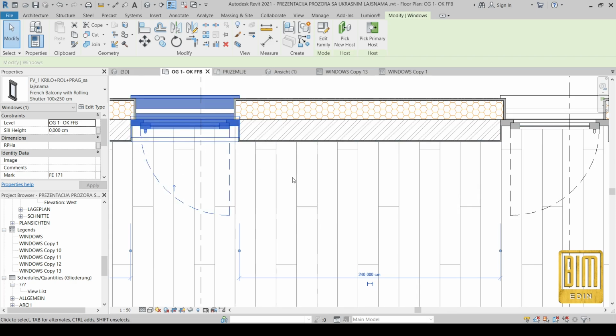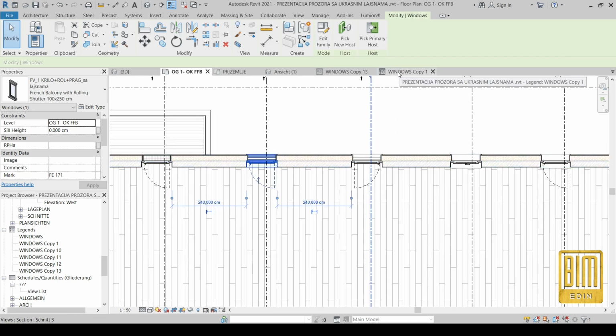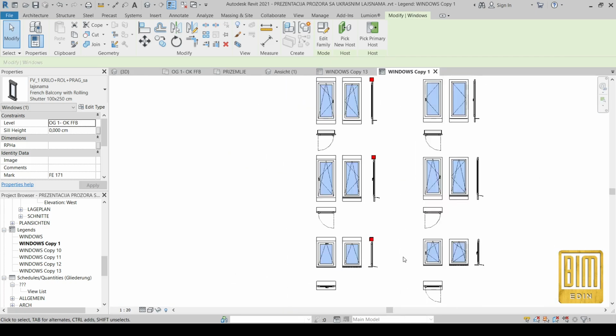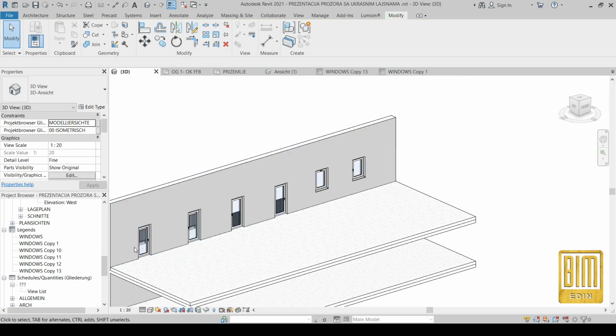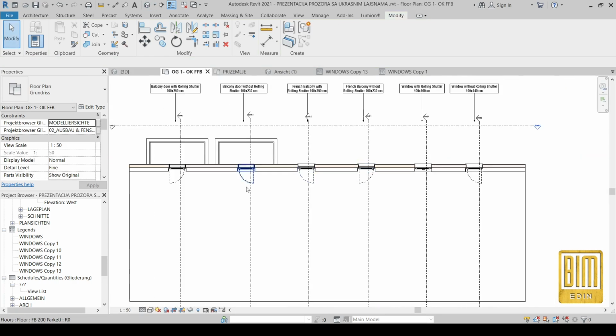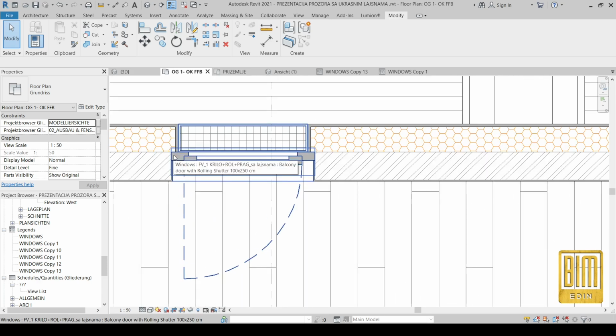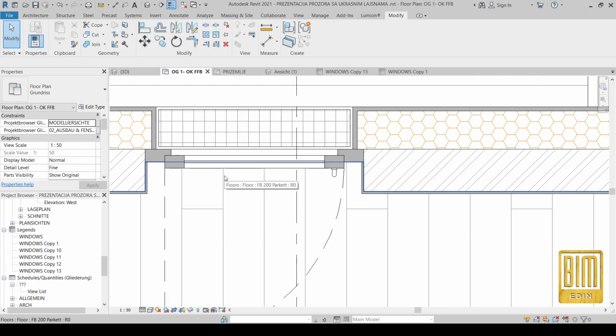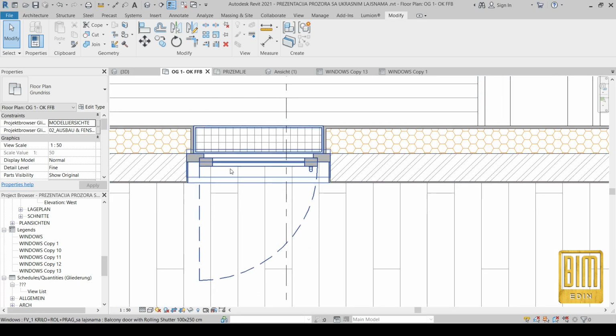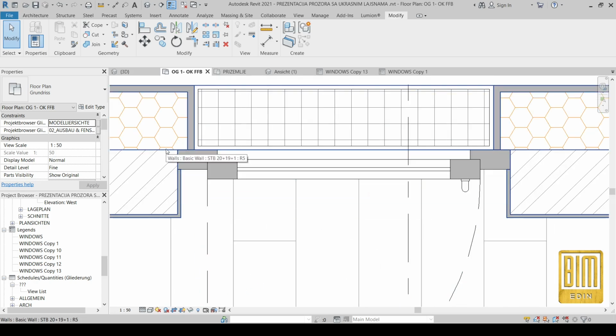Now we will repeat the parameters that this family has. The parameters we are going to create in the next tutorials when we start a series of tutorials on how to create this kind of families in Revit. We are going to have a parameter that moves the window back and forth so that we could place the window on the outside edge of the masonry wall, so that the thermal insulation goes left and right over the window. We are going to have a parameter like that.